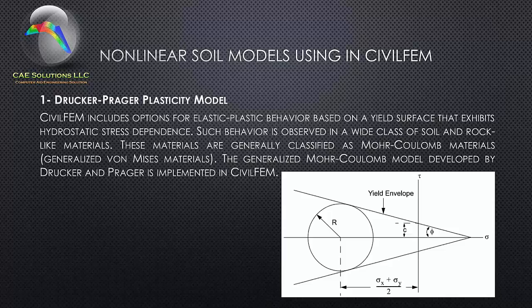These materials are generally classified as Mohr-Coulomb materials, which are generalized von Mises materials. The generalized Mohr-Coulomb model developed by Drucker and Prager is implemented in CivilFEM.